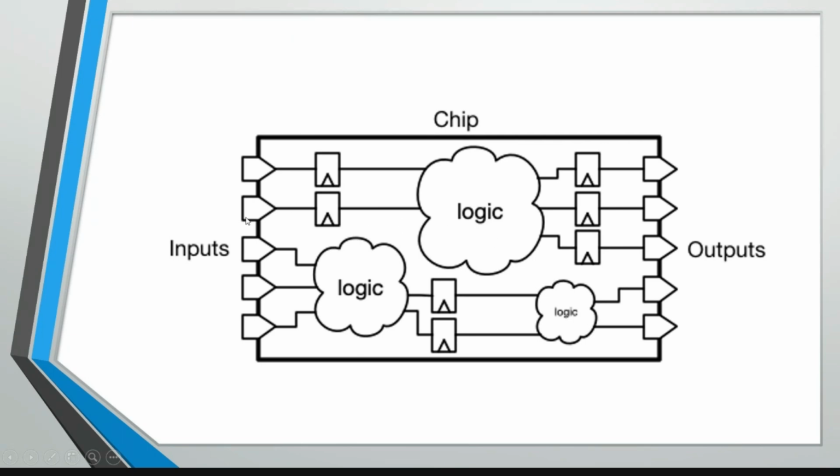Whereas the DFT engineer's role, I'm explaining the two domains just for a clear understanding, is to convert all these flip-flops in the existing design into DFT architecture flip-flops. Those are called scannable flip-flops. That mechanism you can learn later in the course.